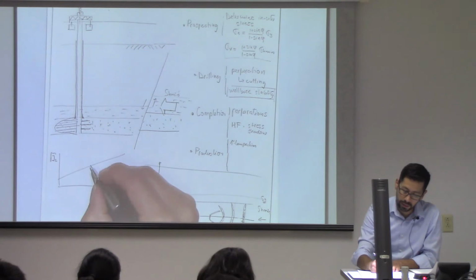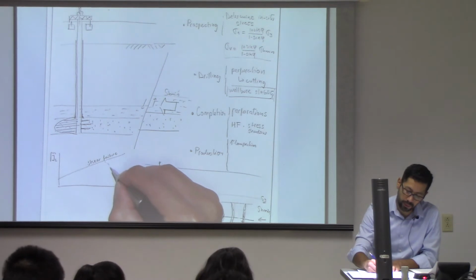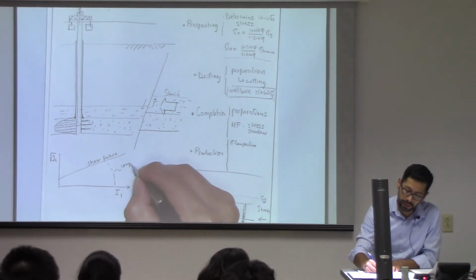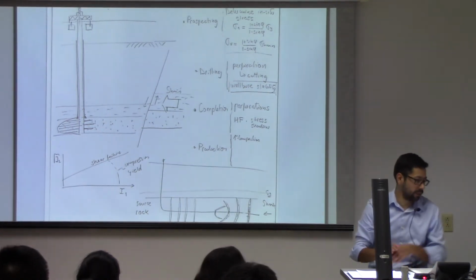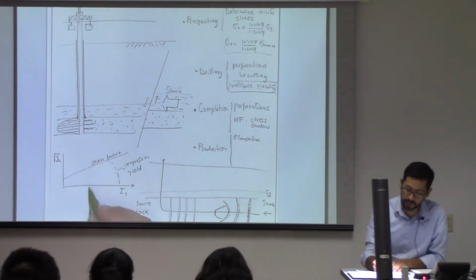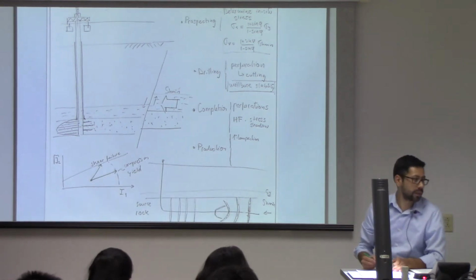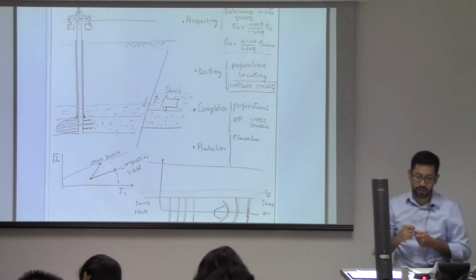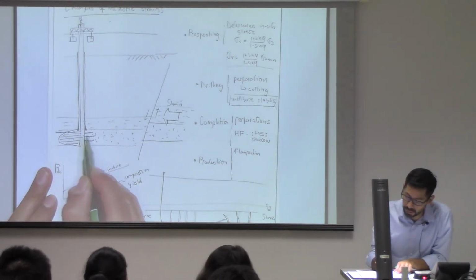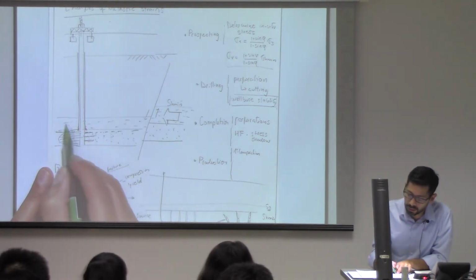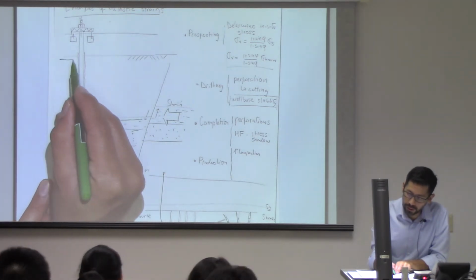And we said that if this is the shear failure, and here we had a compression yield, then either if you start somewhere over here and you go through this limit, or you go into that limit, you're going to experience inelastic strains. And if you experience inelastic strains, again, this formation is going to get thinner,